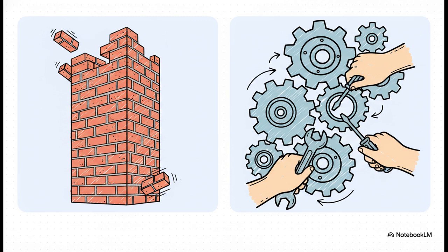Or you can go bare metal. That means manipulating the registers directly based on that reference manual for highly optimized absolute control. Knowing whether to use a layered RTOS state machine with the HAL or raw bare metal drivers is going to dictate the entire software architecture of your product.